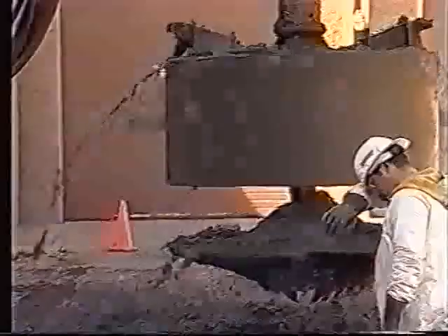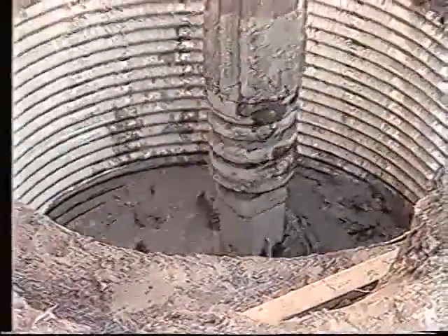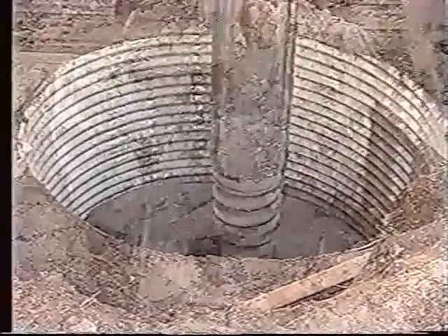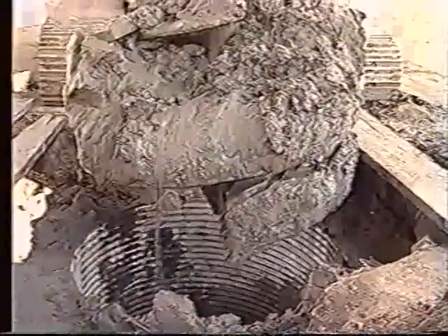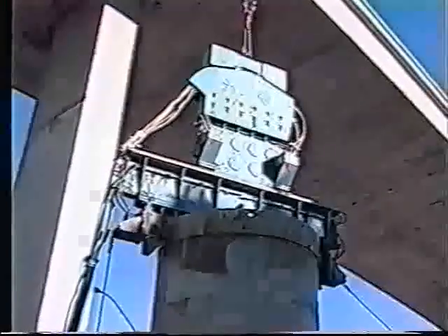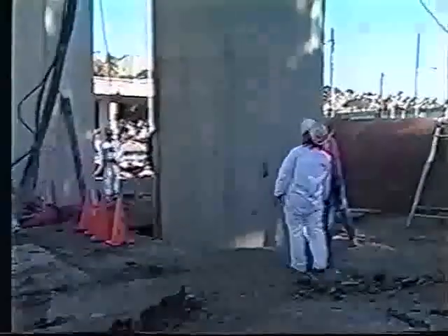When caving soils are encountered, the hole may be kept open by using drilling slurry or casings. The slurry method can consist of circulated water suspensions, or mineral and polymer slurries may be added. A casing can be placed in the hole by an impact or vibratory hammer to support the excavation. If necessary, the steel casings are joined by welding and separated when the temporary casing is removed after concreting of the shaft.